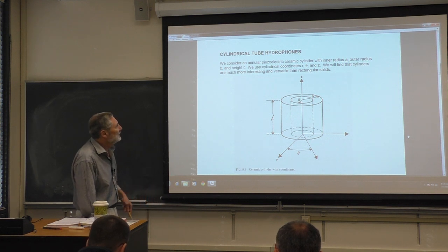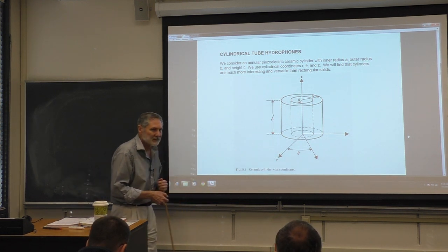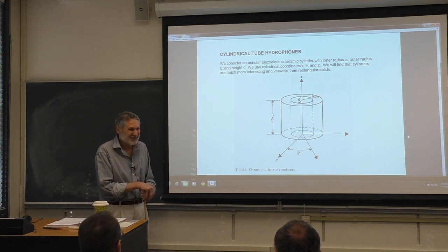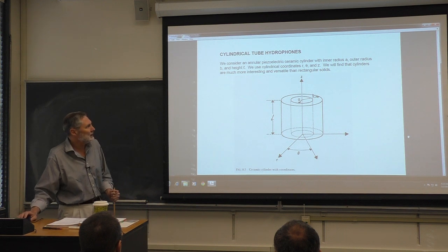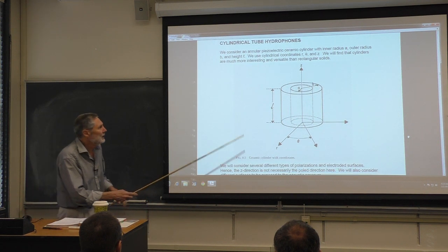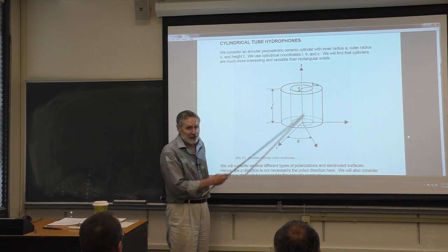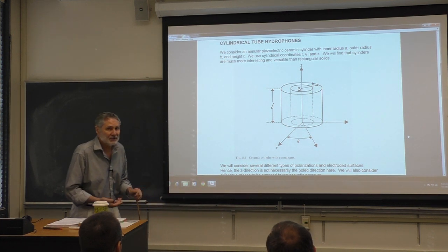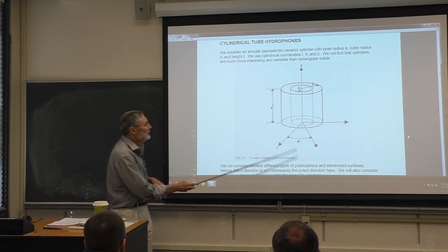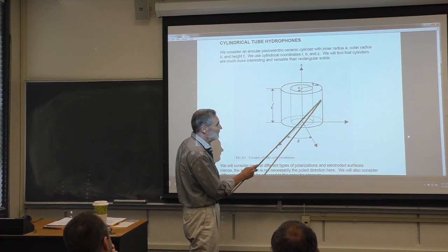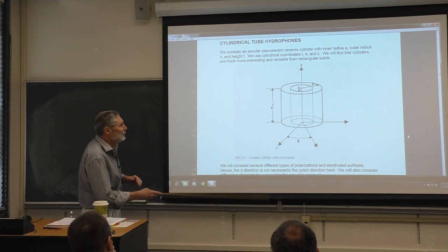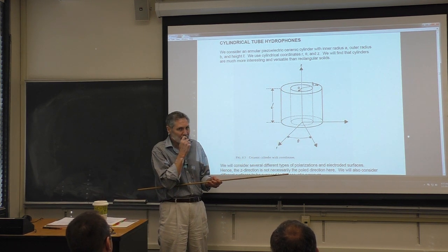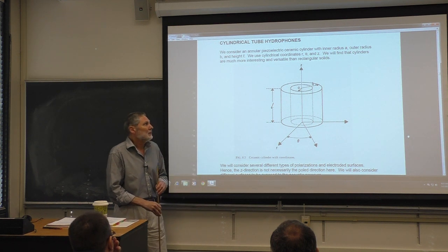Okay. So this is the Z direction. The Z direction is going to be the axis of symmetry. Now there's a little bit of a problem here, and I'll remind you when we get deeper into this. We don't necessarily want to polarize it in the Z direction and electrode it, but we want to be able to deal with other possibilities. For example, polarizing it radially and electroding the inner and outer cylindrical surfaces. We will keep calling this the z-axis even when we have radial polarization. So it's a little bit of a problem, but people get around it.